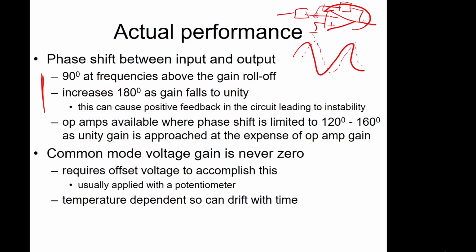If you have a 180 degree phase shift on your output signal, then that is essentially multiplying it by -1. So your output is negated, but it is going in as negative feedback. So essentially what you have is positive feedback. So if you get a phase shift of 180 degrees, your negative feedback becomes positive feedback, and then your circuit becomes unstable.